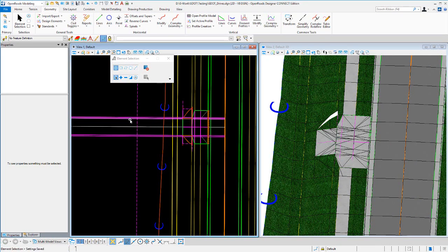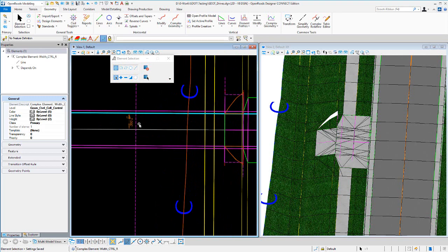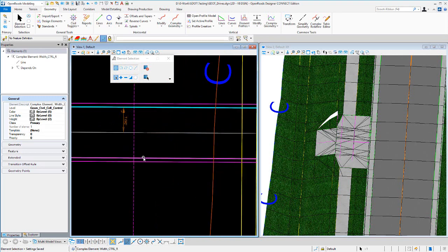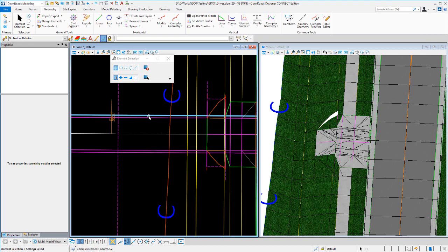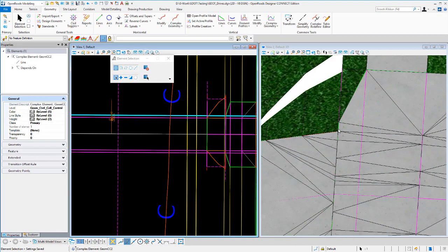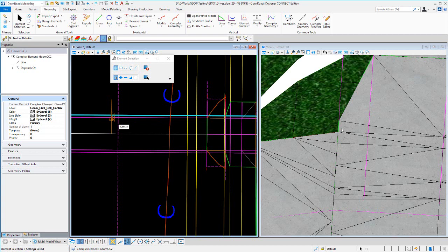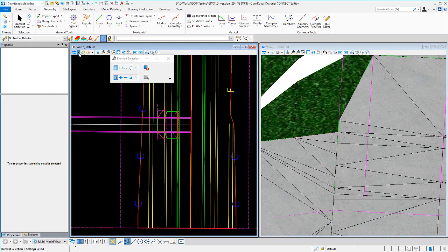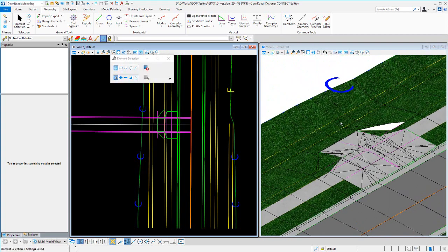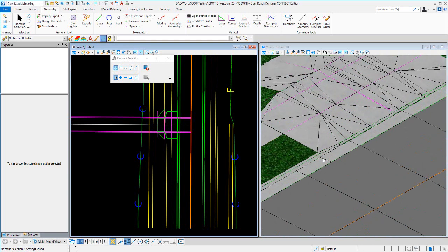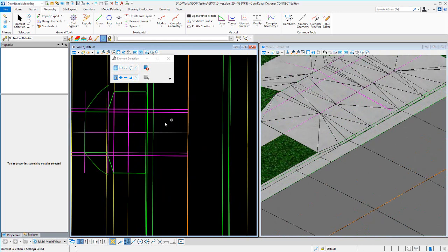Okay, so as the width control is right here, 7 feet, 14-foot drive initially. I think that's a minimum for this type driveway. I'm not going to change that. There's also a 1 foot that can be added to there that controls that little offset there. Alright, then I'm going to turn off construction class, and we'll look at this element, or this area right in here, your curve transition area.